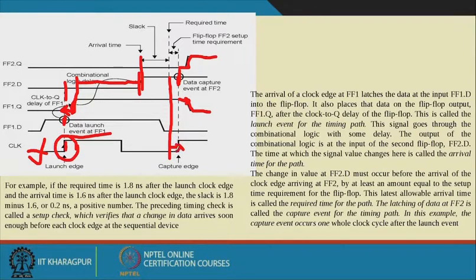But the required time is this one, because this is the setup time. Here this clock edge occurs, and this is the setup time. Before that, the data should be stable, and the data is stable much before that.